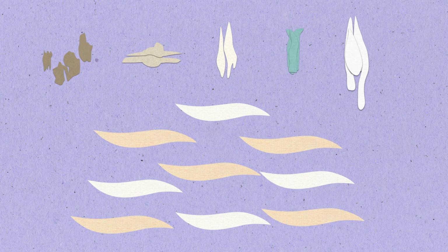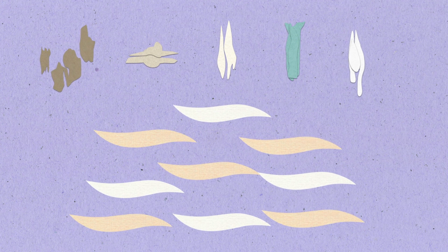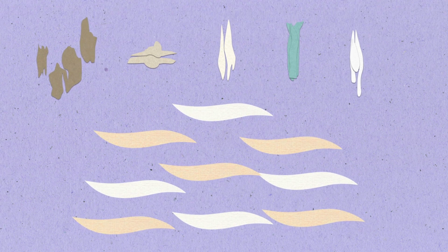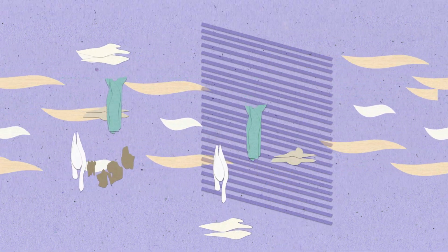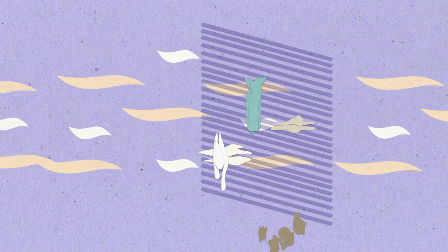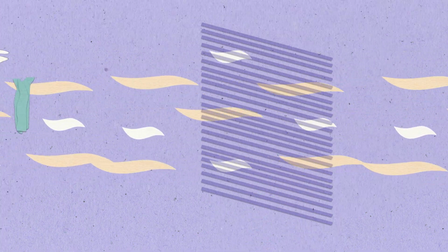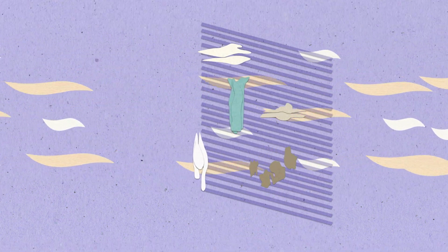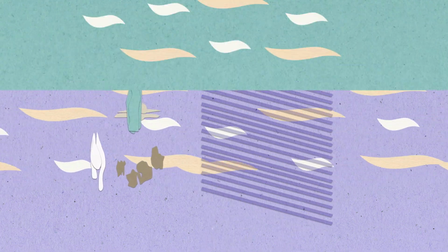There are always some unwanted objects in the pulp, such as bark, knots, sand, plastic, and stickies. These particles lower the quality of the product and can cause web breaks. That's why furnish must be screened and cleaned before making paper out of it. For optimum efficiency of the screening, the right stock consistency is critical. If it is too high, there is a risk of blocking the screen, and if it is too low, it may create a bottleneck in production.